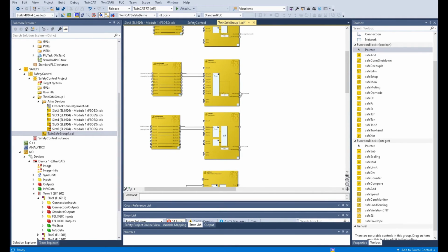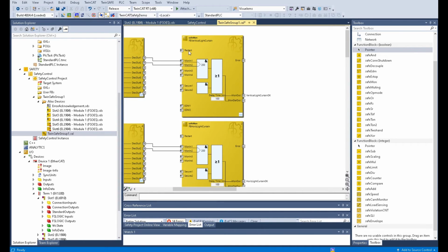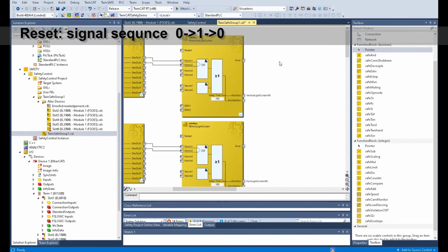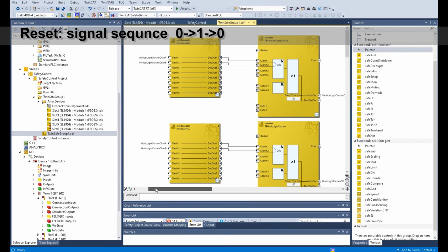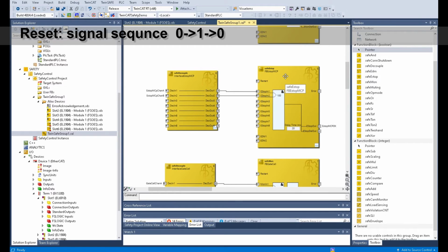That is the reset signal. That is the manual reset signal for the safety input components. Usually, we must use the manual reset rather than the automatic reset. Take the EStop as an example. If the EStop both channels are already on, for example, this output already on, and once the EStop is pressed, the output signal will drop.